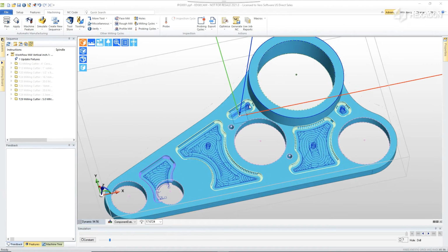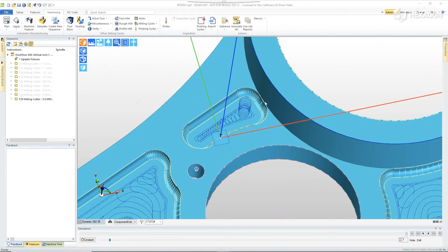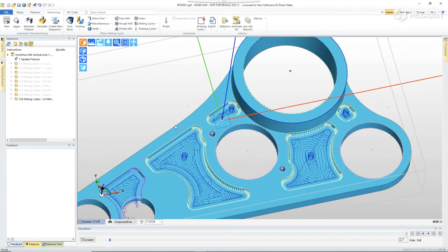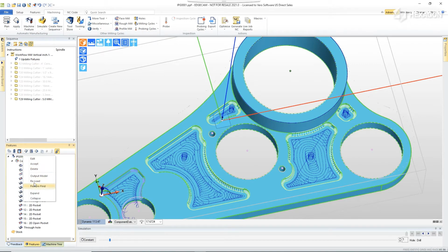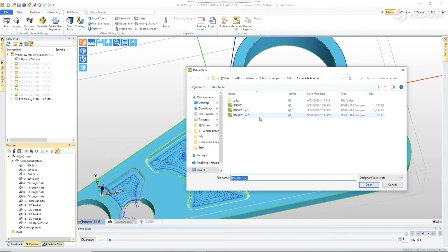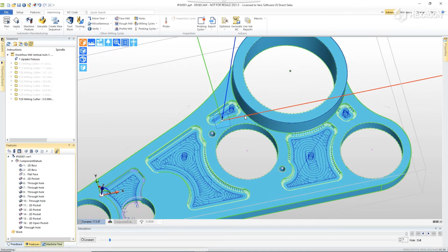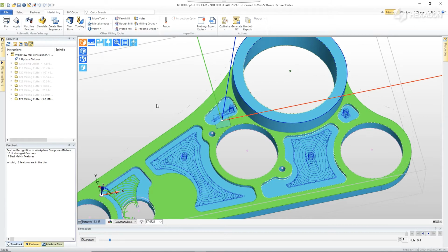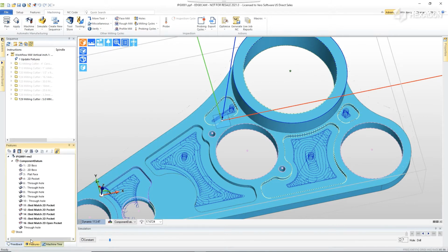So toolpath for the machining operations is completed, but during that process we noticed that some of the weight reduction pockets in the new design join directly against the hub. This isn't ideal and could be improved. We've talked to the design engineer and there's been another design change. So as before, we'll simply reload the latest solid. The updated model is swapped in and EDGECAM immediately evaluates the features. These changes do not affect our current machining process, so we'll simply accept them and move forward.